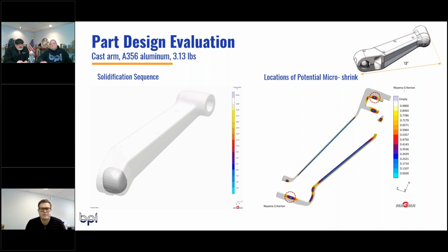That's a great question. And today I'll use the term cross-functional teams that are implemented so that designers don't design anything in a complete vacuum by just looking at structural mechanics and other disciplines that go into developing a functional component. So early in the design stage, there's a material selection process that the designers should go through in conjunction with their purchasing and supplier quality groups in order to understand the best DFM capability of the part and what needs to be done. In other words, can this part be cast in sand, or does it need to be produced in permanent mold? And knowing a little bit about heat transfer and physics and material science, we know that sand may be giving us a part with lower mechanical properties, which I'll talk about in the next slide, versus permanent mold, which is what the designer may be looking for.